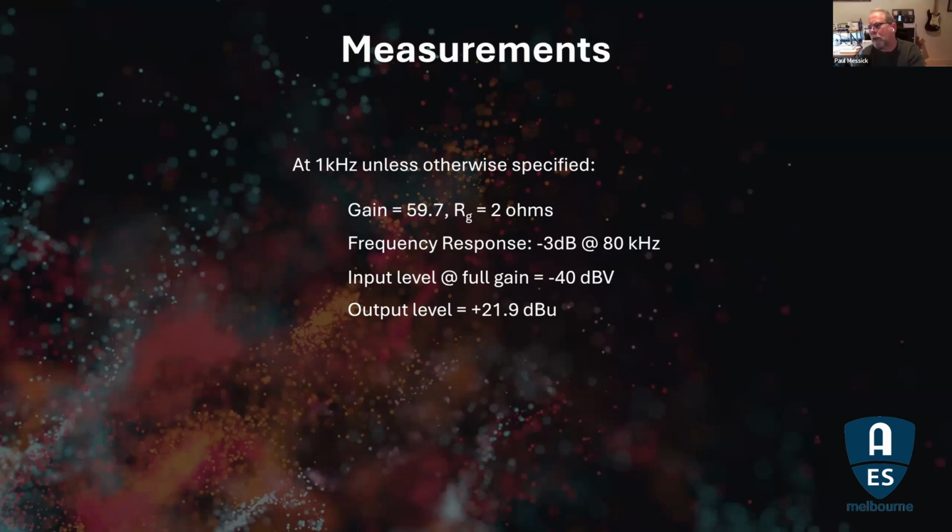It's confusing to me. It might be an interesting topic sometime to do the here's what dB is, because dB is a very confusing thing. Talking about it in terms of volts when it only means power anyway is a little bit of a problem. dBV, I think, is part of the IEC standard and the Australian standard. dBu came out with, I think, Tascam and the Japanese manufacturers. A lot of broadcast equipment about that time, the Neves and those sorts of consoles that were still transformer led, operated at +4 dBm.